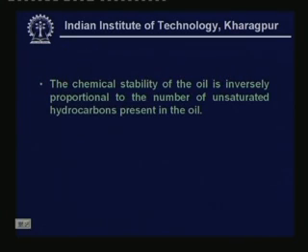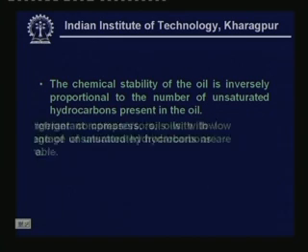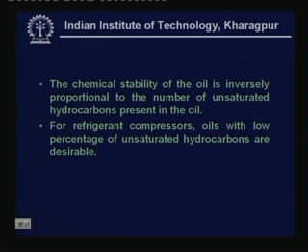So the chemical stability of the oil is inversely proportional to the number of unsaturated hydrocarbons present in the oil. That means higher the number of unsaturated hydrocarbons, smaller is the chemical stability. So for refrigerant compressors, oil with a low percentage of unsaturated hydrocarbons is desirable.